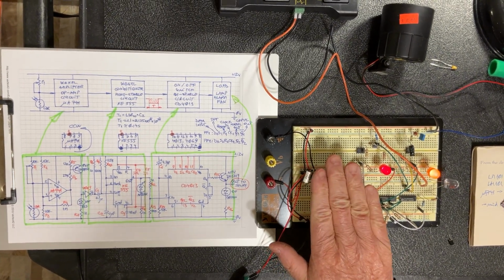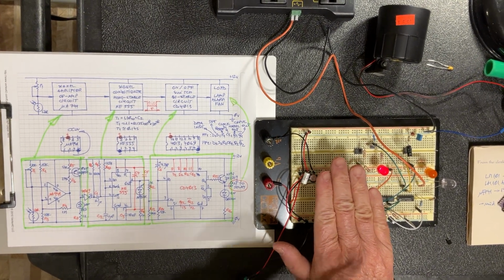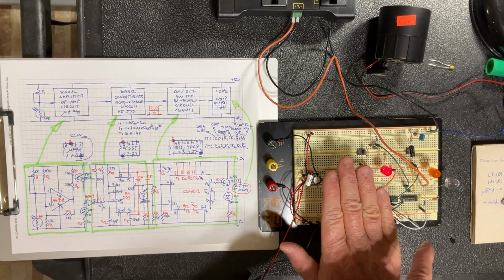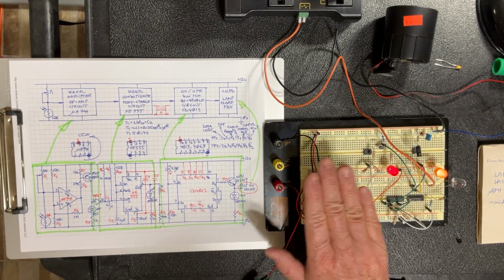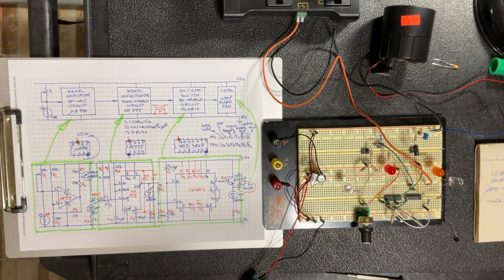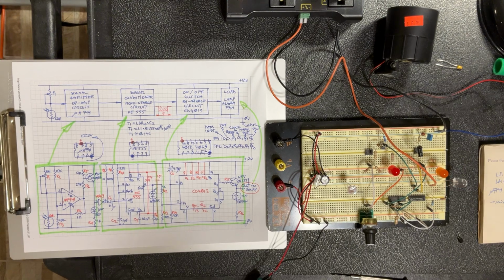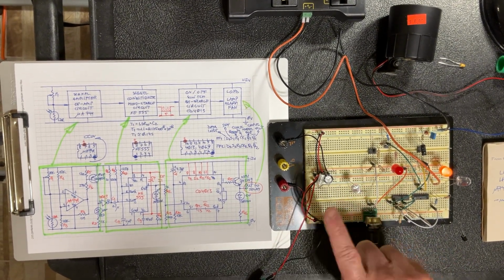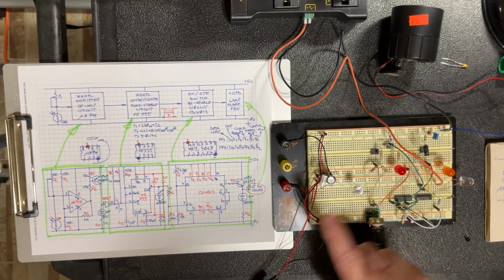So even if I hold my finger on the light dependent resistor, the red light stays on because I covered the light. The amber went off already, because after 1.4 seconds it goes off. And I do this again. And if I do this quickly, it's still holding only for 1.5 seconds. I do this again. But if I continue to do it longer than 1.5 seconds, it's obviously re-triggered after that. So you get this 1.5 seconds again.